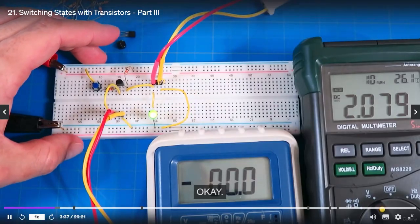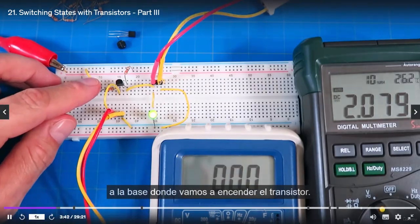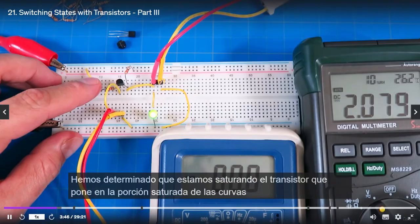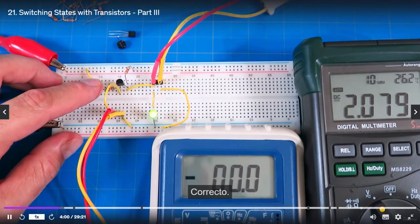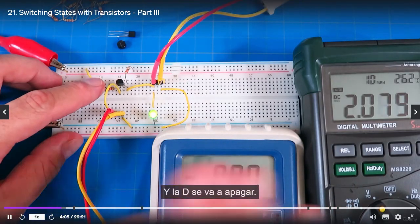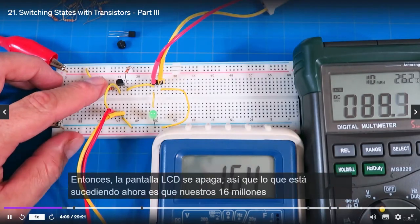Okay. Now, the question is, what happens when I press this button? When I press this button, we're going to inject current into the base and turn the transistor on. We've ascertained we're saturating the transistor, putting it into the saturated portion of the characteristic curves. When it turns on, we're going to get current flowing through it, and it's going to act as another current sink. It's going to pull current away from this LED, and the LED is going to turn off. So the LED turns off now.